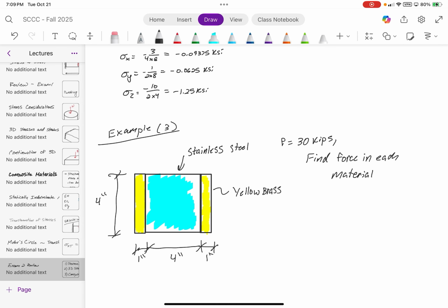Right, so then this would just be P steel is equal to P brass times E steel, A steel, length of brass, divided by E brass, A brass, length of steel. I think it's something like that. I'm kind of rushing through it. I believe it's this, but you can see how I got from this point to this point, right? Always start off with the most basic equation and work your way through it. Alright. Which is not bad.